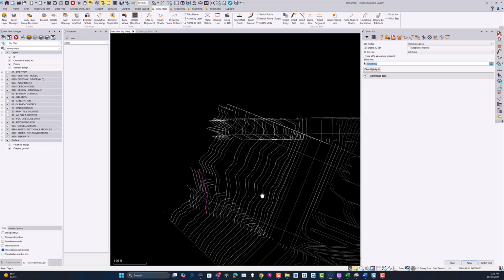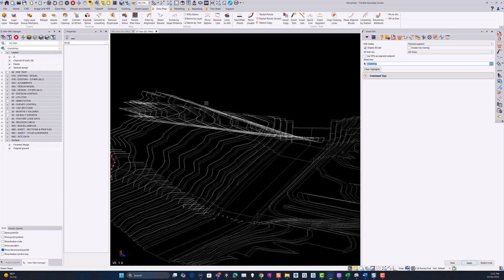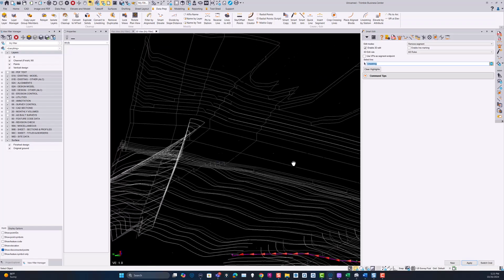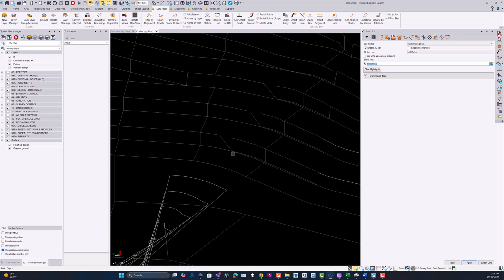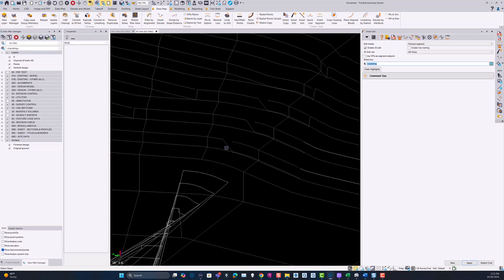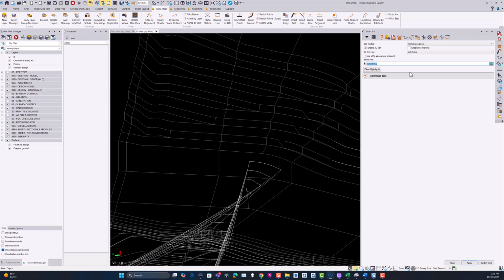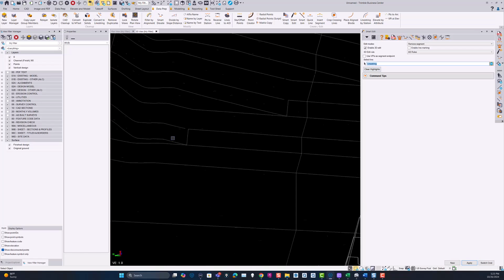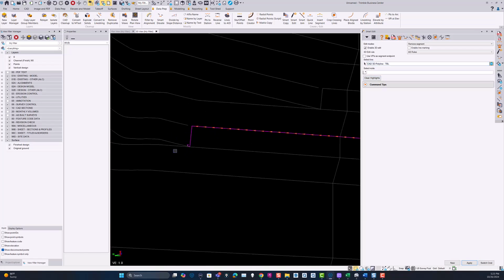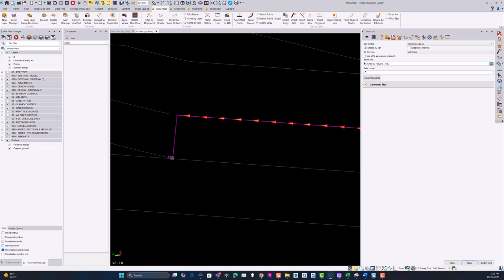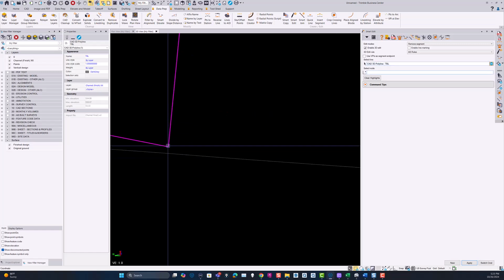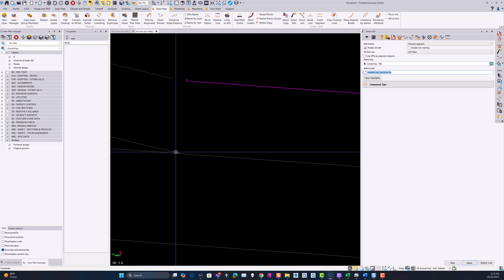Now once you've done those, then you would then switch maybe into 3D mode, and now you want to remove some of these line segments over here. Next, this is where in TBC if you click here it might remove the segment before or the segment after, and it's a bit of a crapshoot as to which one it does. And so one of the things that you want to be able to do in here is when you click on a line segment, it highlights the direction in the 3D view. So we know this is the direction of the line, and then we just click on the end of the line here. So we click on the line to pick it. So first of all we pick the line, and then we click on the node that we want to remove, this one, and that gets rid of it and leaves that little segment in place.